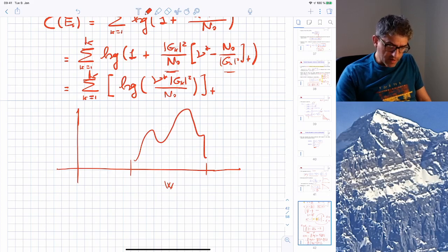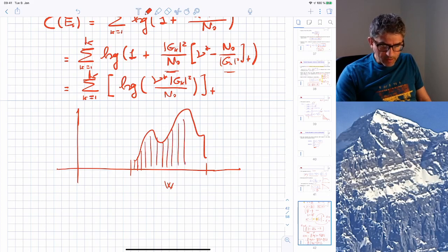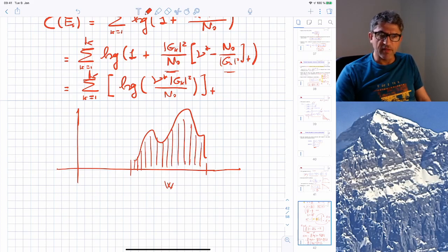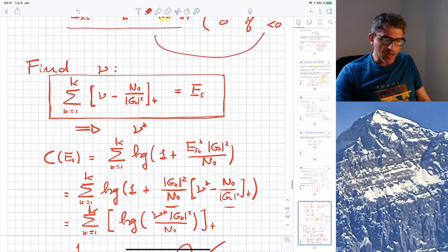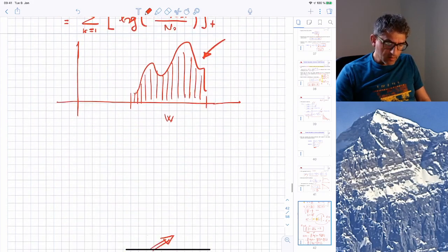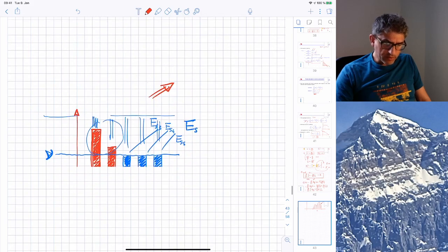So it has a transfer function for which, if I slice this into many small parallel channels over frequency, they have very different gains. Some of them have very good gain, some of them have very bad gain. And then what do you do? Well, you need to do bit loading, which is allocating the total power budget over these channels, and this is done more or less, with some limitation due to practicality, by the Shannon water filling solution.